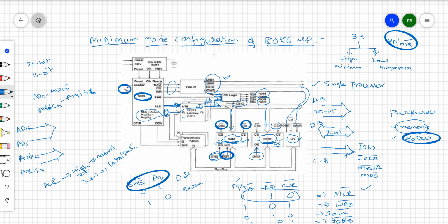That is the reason the data in the data bus is written into this location. If read is activated, whatever data is in the selected register location is read. You all know that once it is addressed in the first T state by the 8086 processor, ALE becomes low. Then this path is closed, and the data bus is activated through the bidirectional buffer, that is the transceiver.